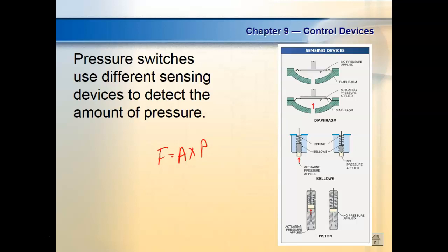If we just say, okay, it's going to get to a certain point to trigger, like the pressure sensor on your compressor, when it gets below around 70 psi, it does what? Turns it on, right? Not at 70, around. And if it gets above 100, it usually does what? Cuts it off.